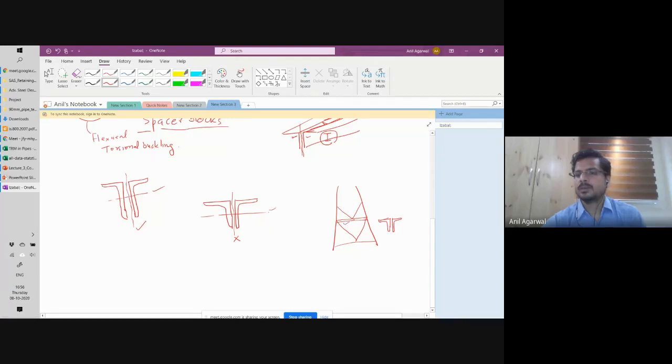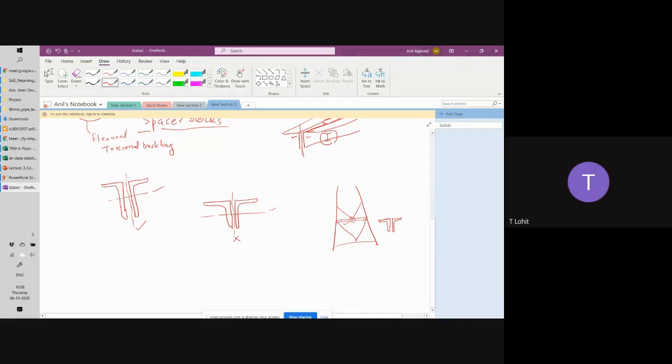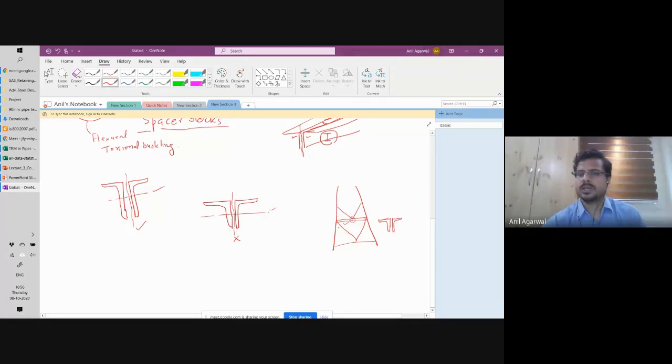Now when the question of buckling comes, it can buckle. What will be the effective length, or let's say what will be the restraint condition here when it comes to buckling? Will these braces restrain its movement up or down? They will, right? Yes, sir. Right. So then the length that you should consider is only this much for up-down movement.